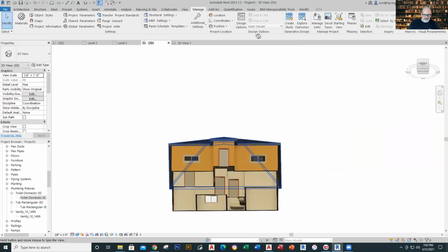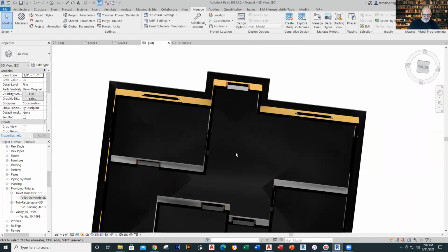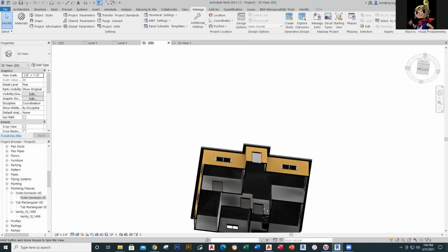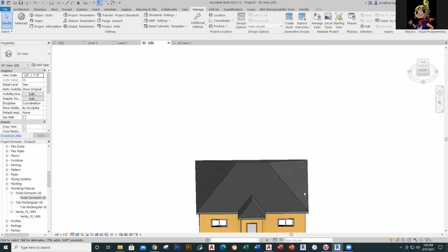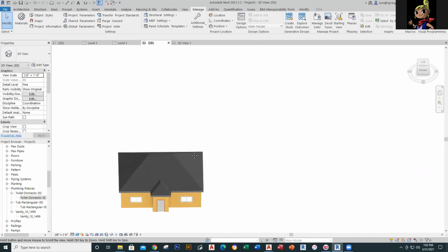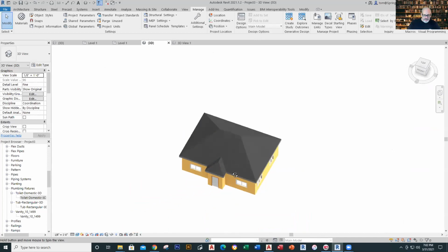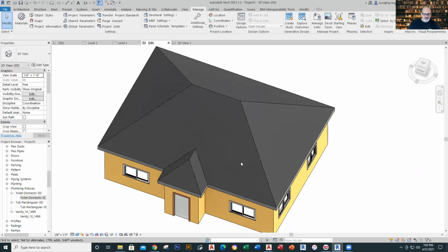Interesting. Let me look underneath it, see if it's applied. How do you get the roof on top of the doorway? I'm having issues with it. Well, all I did was, from the level 2 view, I just picked the walls and went along there, and it generated it automatically. If you're having errors, I'm not going to troubleshoot them right now, but I'll go ahead and show this again.